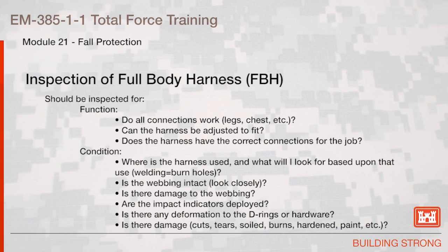Inspection of a full body harness. They should be inspected for function. Do all connections work? Legs, chest, etc.? Can the harness be adjusted to fit? Does the harness have the correct connections for the job? Check for the condition. Where is the harness used, and what will I look for based upon what use?